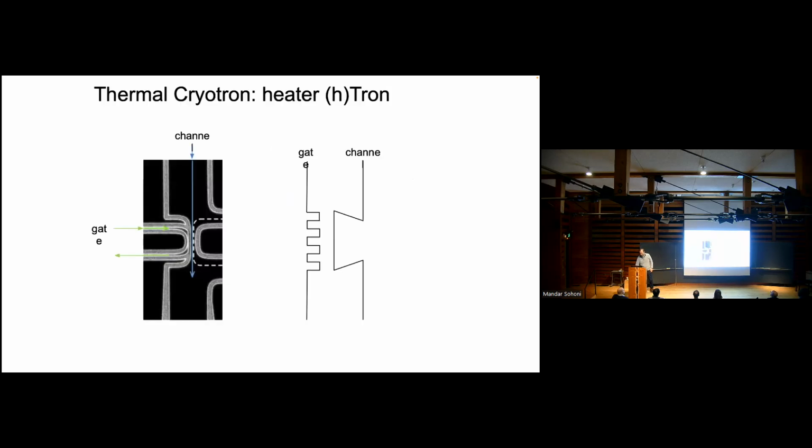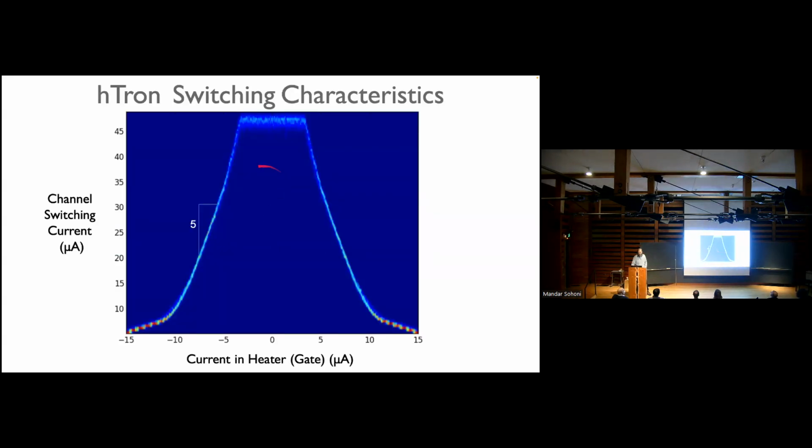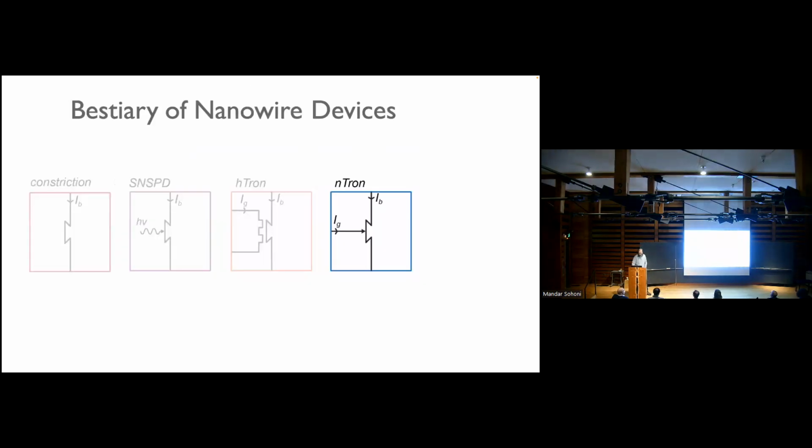And we draw it like this. One of the fun things is we've gotten to invent a bunch of our own circuit symbols. So we've got a heater here, and this gate. The heater transfers energy to the gate. You get a decent gain characteristic here, a differential gain of about a factor of 5. There's plenty to do logic with and build small computers and things like that.